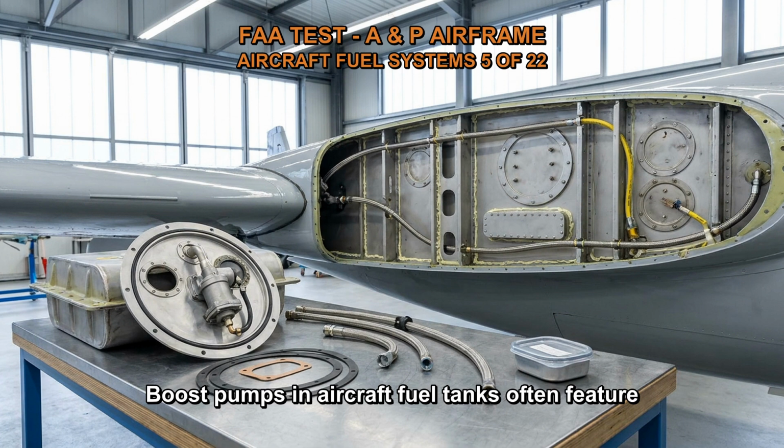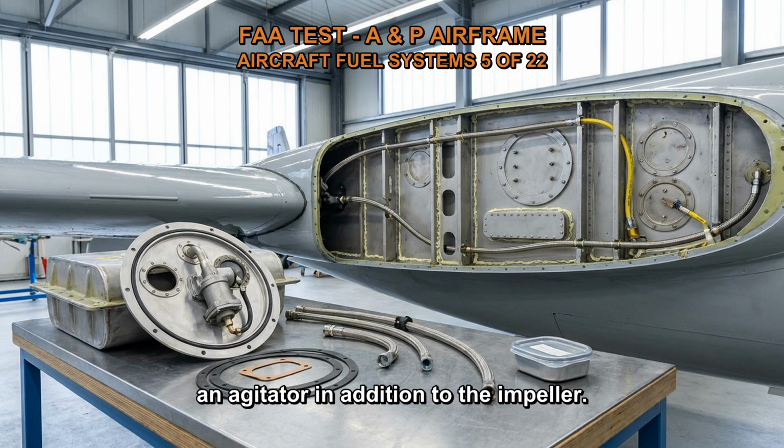Boost pumps in aircraft fuel tanks often feature an agitator in addition to the impeller. The purpose of the agitator is to release any trapped bubbles in the fuel back into the tank before the fuel is pumped into the fuel lines. By doing so, the agitator helps minimize the presence of air bubbles in the fuel system.